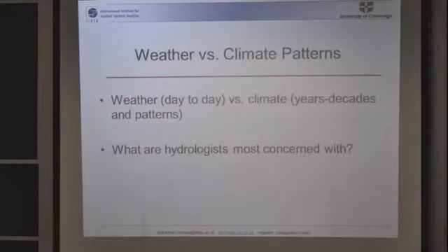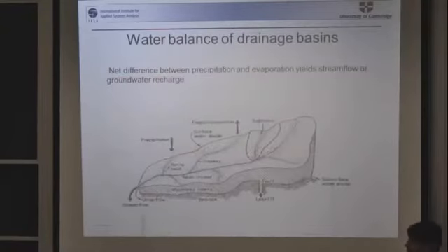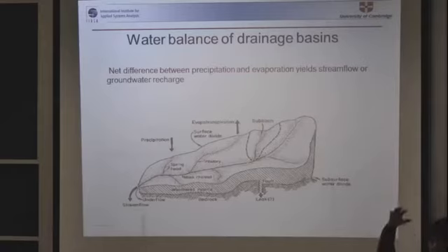There are two terms. Here is precipitation, which is coming downwards from the atmosphere to a catchment. And what is going out? Input should be equal to output. The input is precipitation in sum, and the output is evapotranspiration, which goes outside from the catchment.